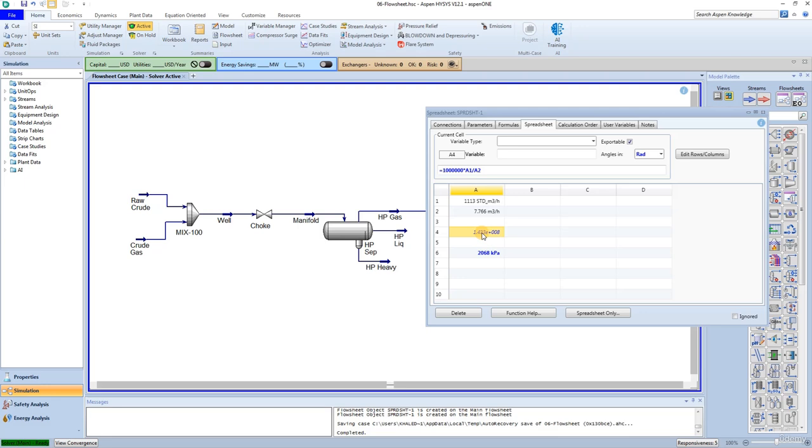Please note that the formula used in this gas-oil ratio calculation example requires you to use English imperial units. The spreadsheet can support a unique unit set different from the remainder of your simulation.